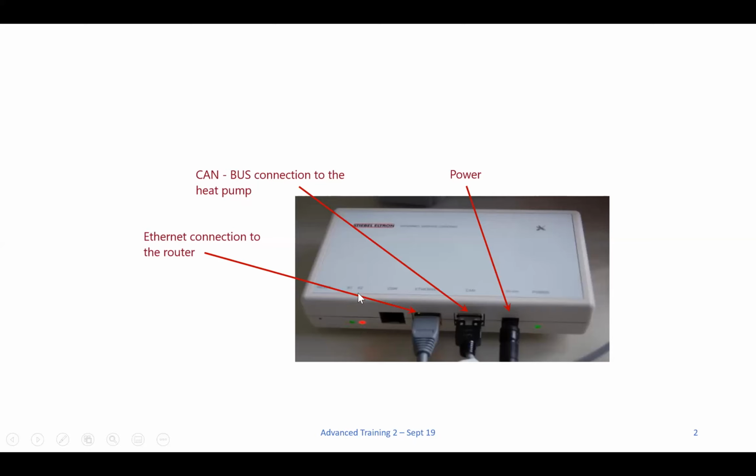So when the ISG is powered up and the Ethernet is plugged in, after a couple of minutes of boot up, the X1 and X2 will start flashing, and then after a couple of minutes, they should steady onto what their indicator is trying to show you. X1 flashing green means communicating with the WPM. X2, if it goes solid red, it means it's found the network.